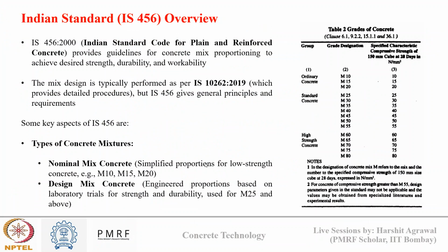Okay. Now, for mixture design, there are two important Indian standards. First is IS 456 and second is IS 10262. So IS 456 is the Indian standard for plain and reinforced concrete. It provides guidelines for concrete mixture proportioning to achieve desired strength, durability, and workability.